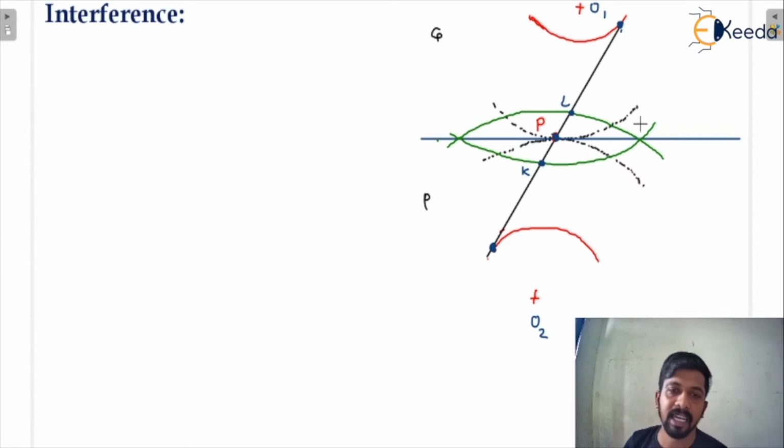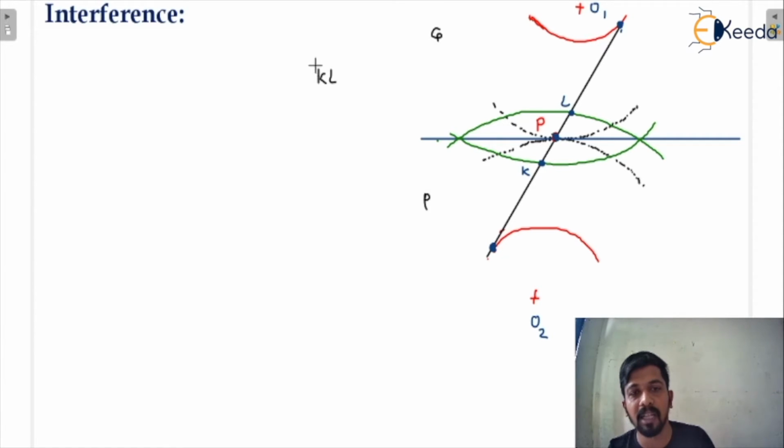And we are studying gears of involute profile. Our profile of gear is involute, so that means there is an involute connection for gear and pinion. Now this is the path of contact. KL, we all know, is considered the path of contact, in which KP is the path of approach and PL is the path of recess.